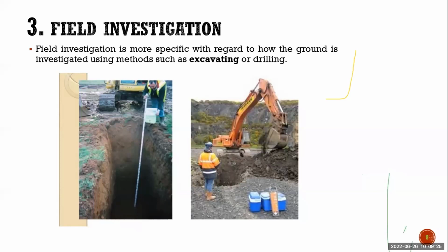Now, then field investigation, it can be either excavation or via drilling. The pro for the excavation is that in the excavation we can see the soil layer very clearly. Let us say minimum 2 meter by 2 meter, and depth up to even 4 to 5 meter also we can excavate with the help of the excavator. Then we will know different soil layers, if there are 2 or 3 different layers. Definitely topsoil will be there. After topsoil, is there 1 layer or 2 more layers, or many layers? We can determine. We can check.